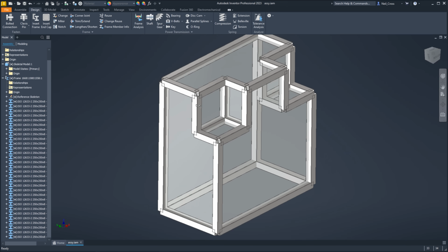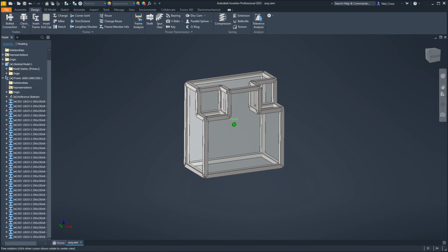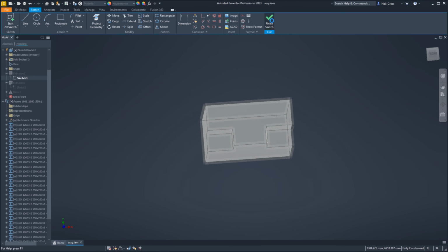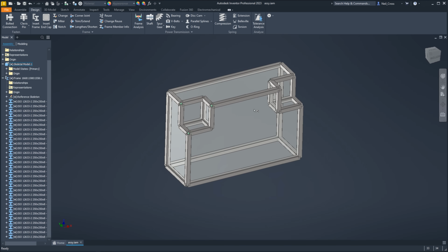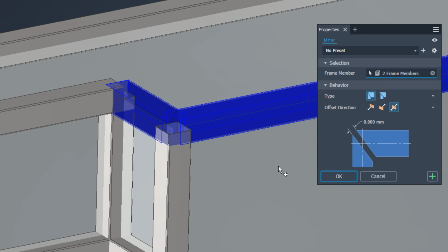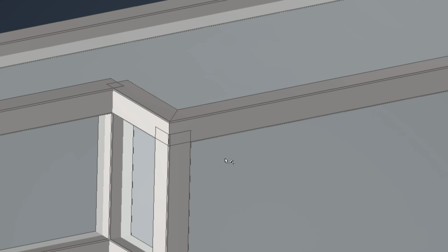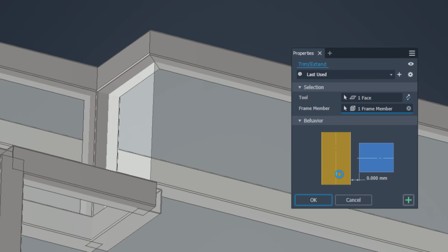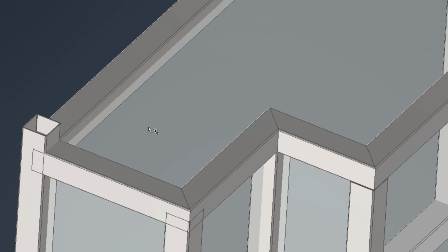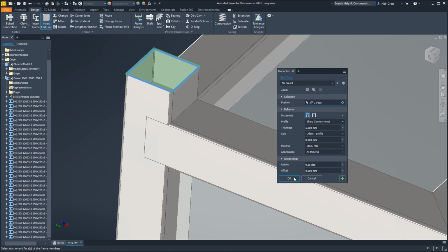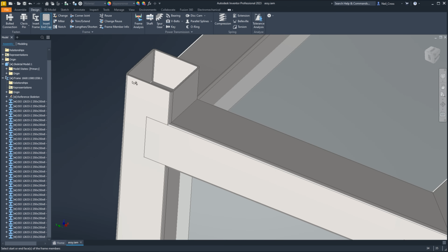But essentially, Inventor has a massive library of international standard profiles which can be placed against a skeletal edge or edges. Inventor then auto-generates frame member solids or parts, itemizes them all up for cutting or parts lists, and you then got, mate, a pretty decent arsenal of treatment tools for mitering corners, trimming frames, notching. You can even drop on end caps onto the frames. This can all be then pushed over into the beam analysis simulation environment for load testing.